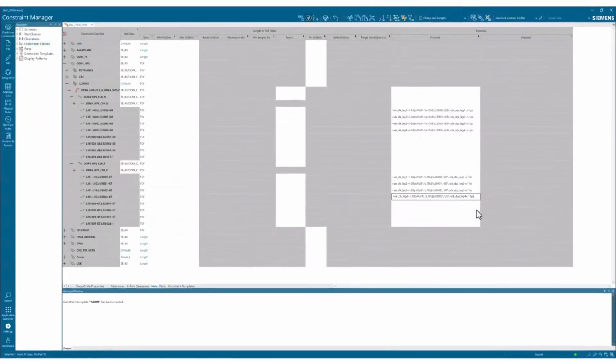So if I wanted to, I could give it 0 picosecond tolerance, in which case clock to strobe leg 1 would just be the exact value of leg 1 of the clock, but I'm giving it a 1 picosecond tolerance just to build a little bit more room into the design. Sometimes it's easier to put a lot of constraints, but when you make them too tight, it can get really difficult to actually route the board. So sometimes it helps to put in your major constraints and then work from there.